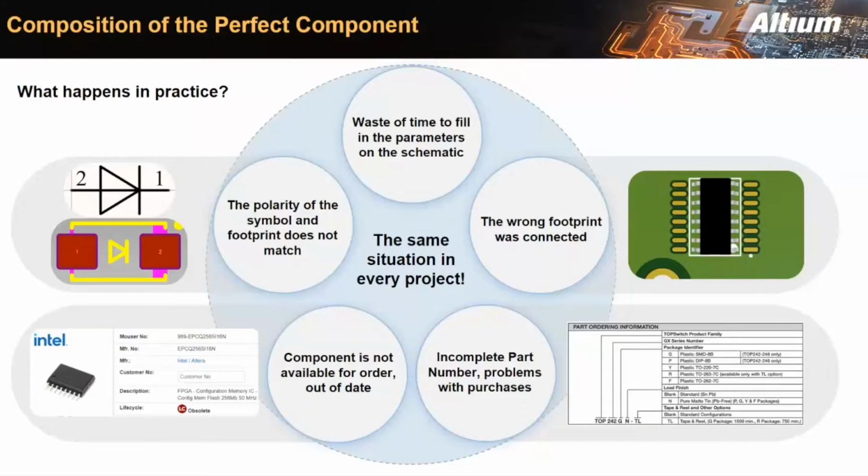For example, a resistor or capacitor symbol is used, and the parameters are already completed in the schematic but not with the proper values. Also, when pursuing a rapid creation of schematic, designers may not associate footprints to symbols as they only need to create a schematic for a deadline. Incorrect footprints can be associated with the components already in the schematic, leading to potential errors.